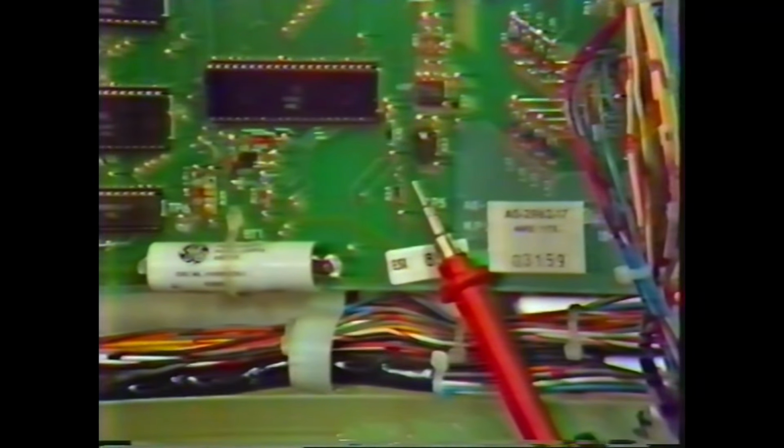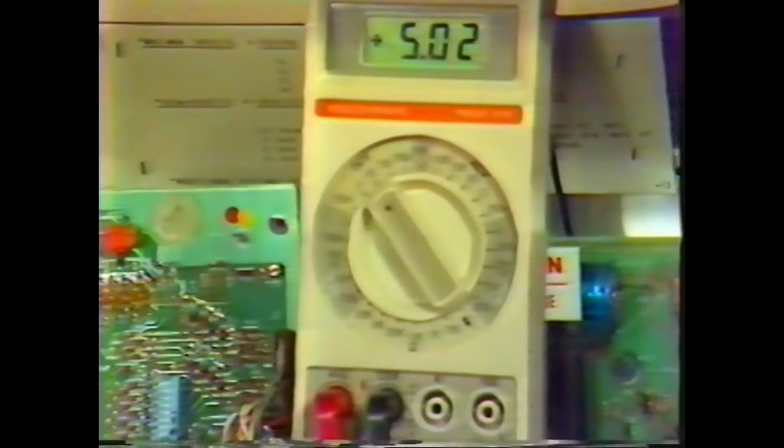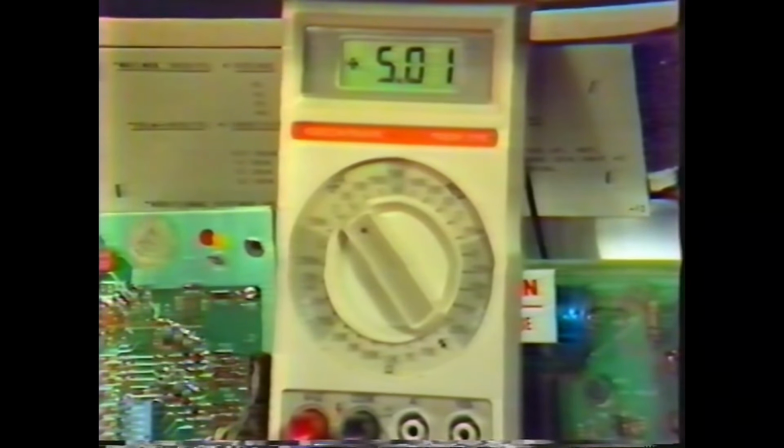All games require a 5-volt power supply to operate, and a pinball machine is no different. In this pinball machine, the 5-volt test point is seen here. It's labeled test point 5 right on the printed circuit board. And with the red lead on the test point, we can read the voltage right off the meter, 5 volts. Don't forget to put your black lead on ground, like the ground braid or the special ground test point.